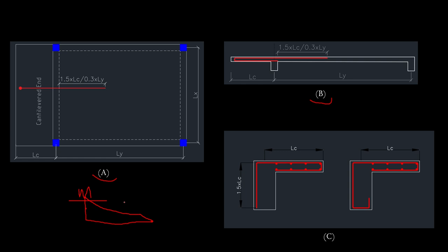top of the slab. So in detailing this reinforcement, we know that this reinforcement is going to span through the cantilever slab. So it's going to start after you've removed the cover for the slab, depending on the design condition or the exposure condition and other factors. So when you remove the cover, then from the cover, you extend the reinforcement throughout the cantilever end, as you can see in figure A. Then it crosses over the beam.